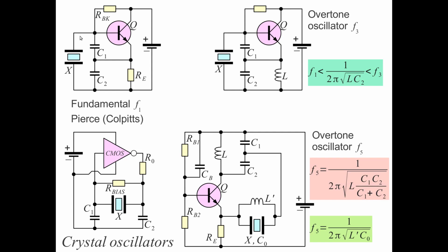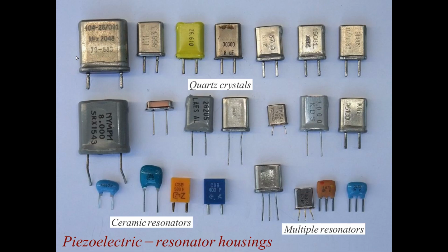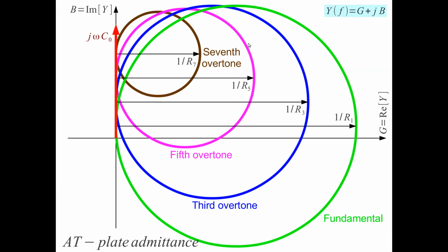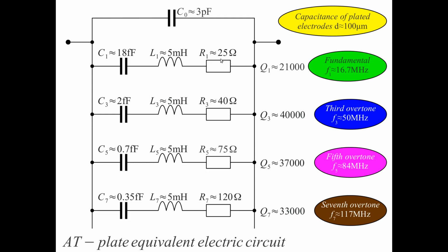An oscillator can be just a simple Colpitts oscillator where the crystal takes the role of the inductor, plus some series capacitors for the DC operating point. This is actually the simplest transistor oscillator, since the series resistance is the lowest for the fundamental mode, not the highest Q, but the lowest series resistance.